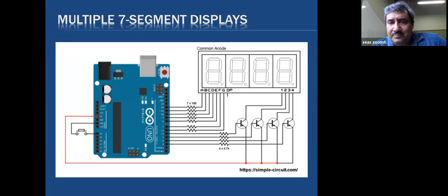In this case we put 4 of them in parallel, and we may control each one individually. So we have 4 of these, 1, 2, 3, 4. We have separate control bits, and then we can share our data lines with all the LEDs, and we can do the programming of multiple of them.